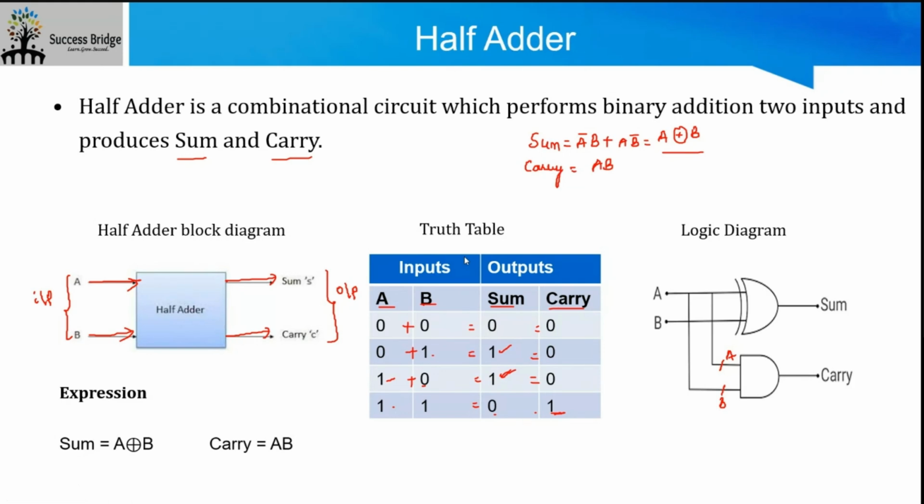And the equation of sum and carry: A XOR B, which is A' B plus A B', and carry is just A B, which is an AND gate, the same representation of your logical gates here.